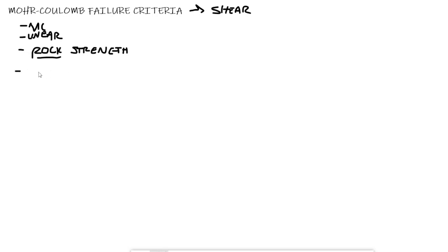And it is used to predict the strength of rock, the compressive strength of that rock with changing confinement. And when we talk about confinement, we're talking about that pressure, right, that's applied around any rock that isn't in that principal direction. When we think of the principal direction, we're thinking of maybe the vertical stress from the weight of the rock, and then the confining stress or pressure is everything that's surrounding it, right?